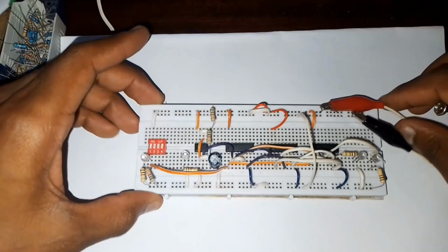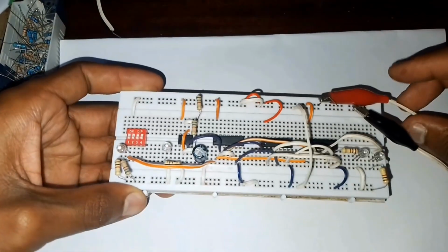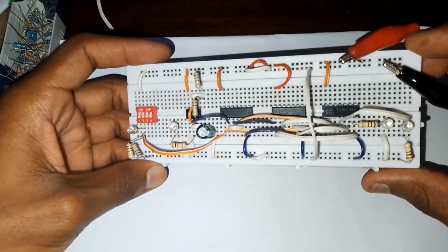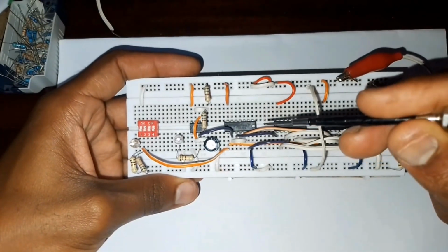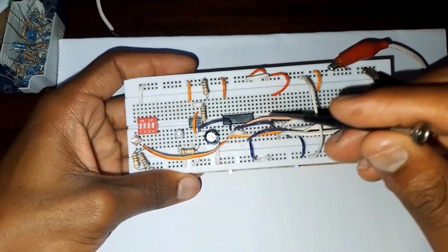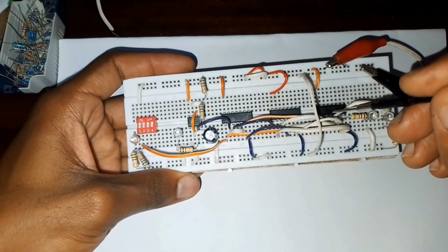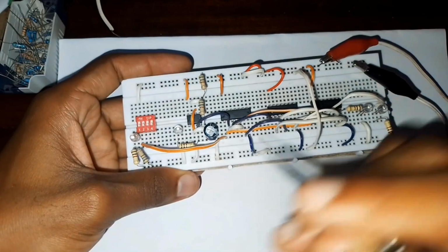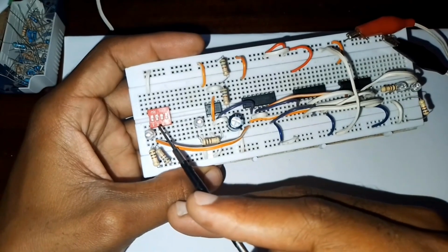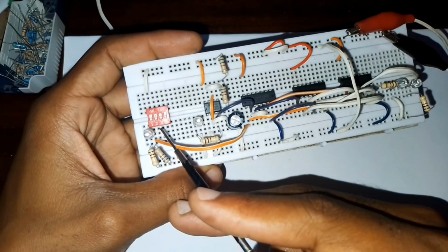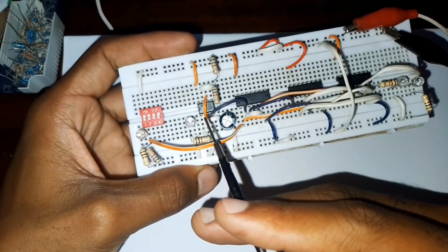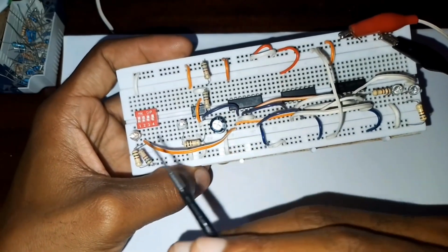So guys, this is the demonstration of the set and reset latch simulation that we have just showed you. It's pretty simple. You're going to require three logic gates: the AND gate, the OR gate, and the NOT gate to make the circuit work. My input section is right here. For the data, I'm using a dip switch. For the clock signal, I'm using an NE555 in oscillator mode. And so those are the input sections.